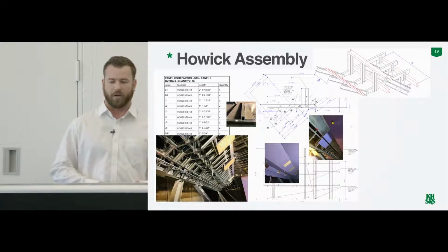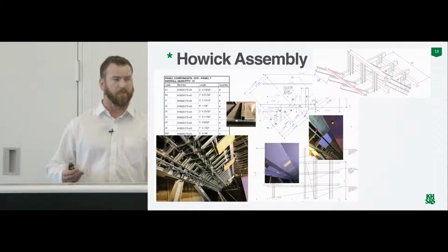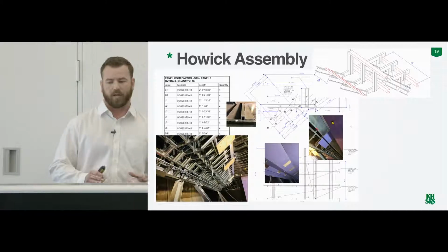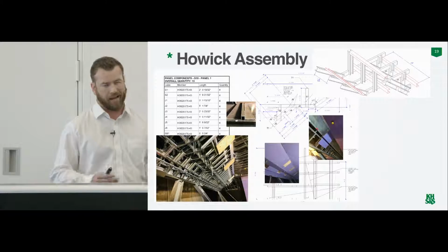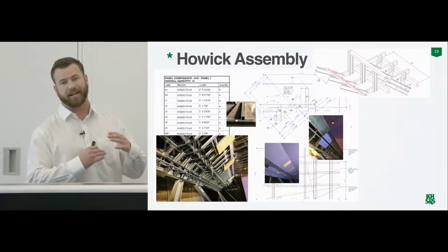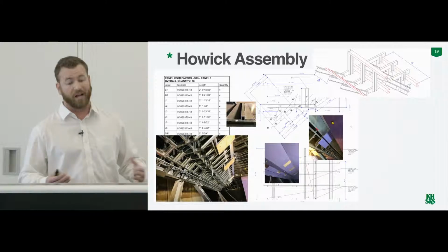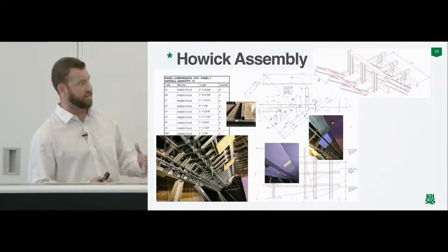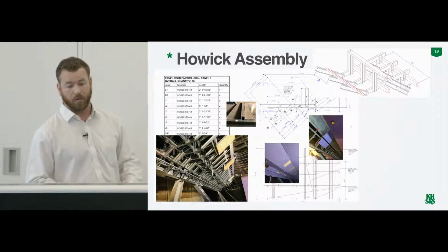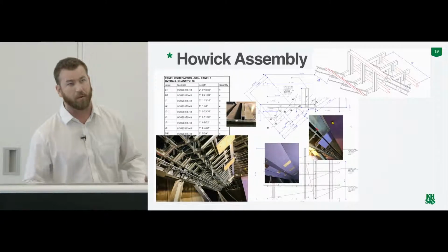We found in history that the majority of clashes are with walls. So with ductwork, it hasn't really been a value to say we're going to model every single stud in the ceiling. It doesn't make sense. So we do model a plane, a placeholder essentially for the ceiling that has the thickness. Long story short, we can't output information from the model that we don't have model information for, right?